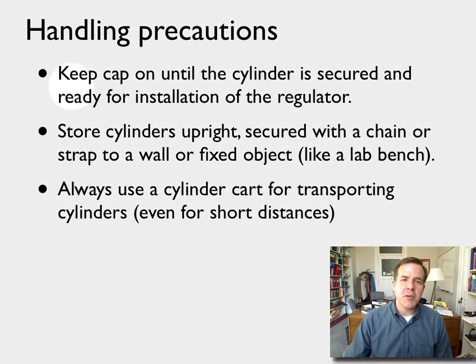One of the most important rules is that we always keep the cap on the cylinder until the cylinder is secured and it's ready for installation of the regulator. This minimizes the chance that if something should happen to the cylinder, if it should be knocked over or fall, that the valve would be knocked off. We always store cylinders upright, never lying down on the floor, and they always must be secured with a chain or a strap to a wall or other fixed object, such as a lab bench.